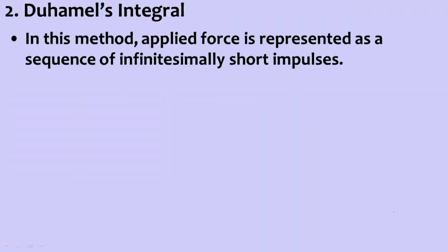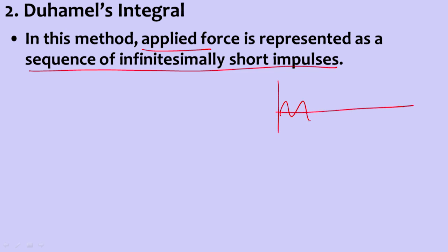The second method is called Duhamel's integral. In this method, whatever externally applied force is there is divided into several components. The applied force is represented as a sequence of infinitesimally short impulses. For example, if the applied force is like this, as input motion, then it can be divided into small components, and each component is taken separately and solved, and later all of them can be added by using the superposition principle.